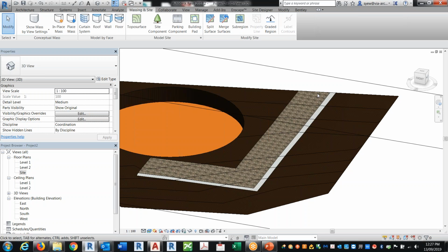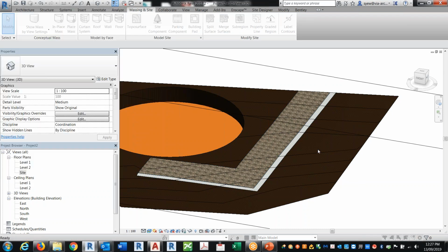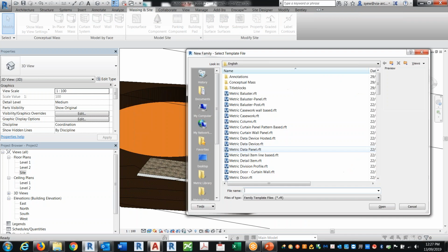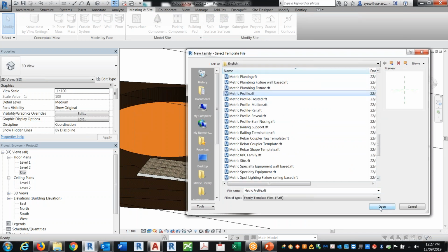One way I do it is using what's known as a railing. So you can create a railing profile that is like a sidewalk width, and all you have to do is make it sit on top of this topo surface, and it will just follow that. Okay, so maybe I should just do that simple demonstration. Let's assume you want to do a sidewalk in this particular one using railing. The first thing you do is create a profile, just any profile you want. I usually start with the generic one.